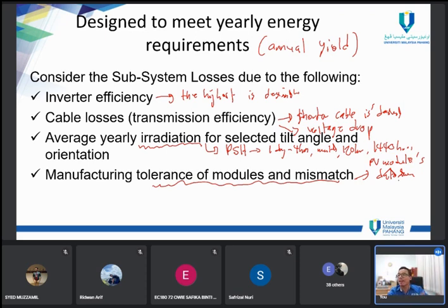Usually, it's written in plus and minus. For example, plus and minus 3% of tolerance. Okay, there are other words also: manufacturing tolerance, power tolerance, tolerance. As a way to track it, usually it is very near to the value of the PMP in the datasheet. They write plus minus 3%, sometimes 5%, sometimes plus 5% minus 0. Sometimes they have that kind of values.